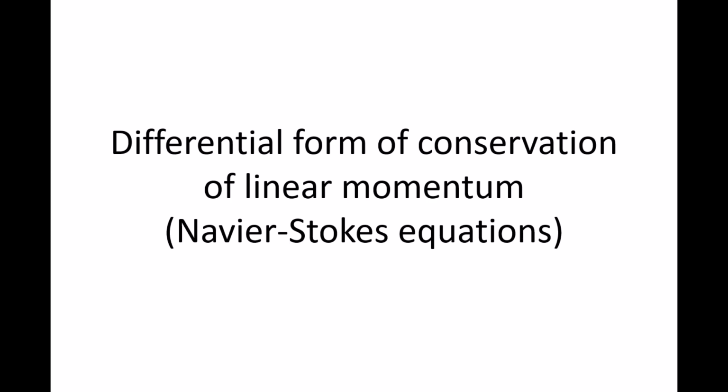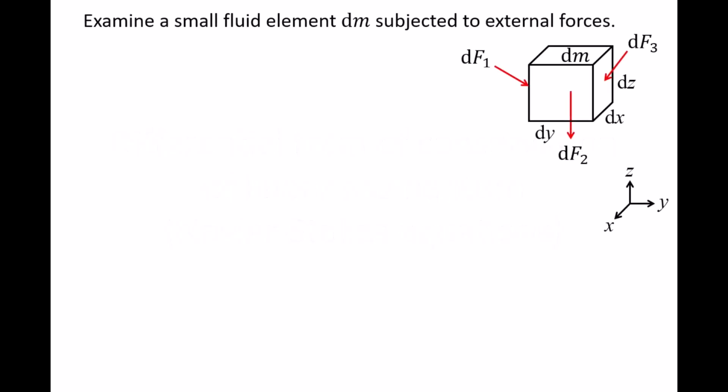In this lesson, we will derive the differential form of the conservation of linear momentum equations for a control volume, which are commonly called the Navier-Stokes equations. Here we have a small fluid element of dimensions dx, dy, dz, and a mass dm.